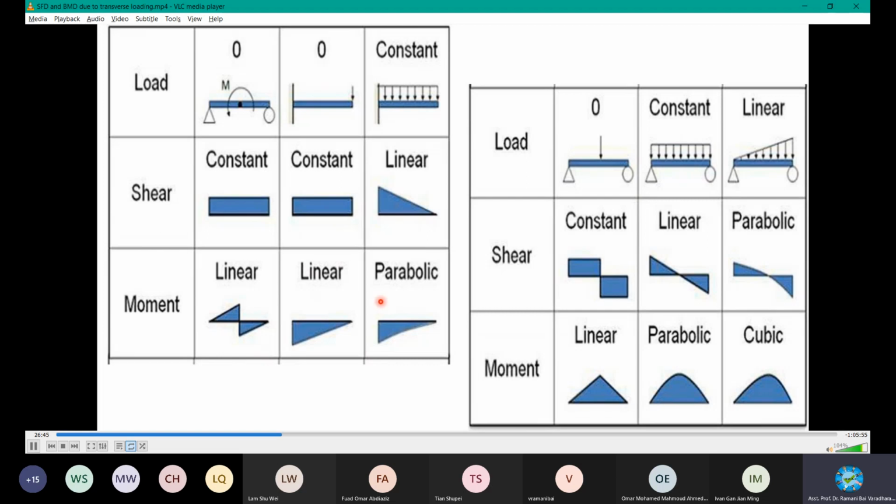And then UDL, start from here. Again, because of the fixed end, you will have a fixed end moment, the resistive moment. Thus, you have some value which is hogging type. Both cantilevers are hogging type, that's why it's negative at the bottom. You can follow either positive or negative, it depends on your convention. So start from here, some maximum value, and then it is slowly reducing.